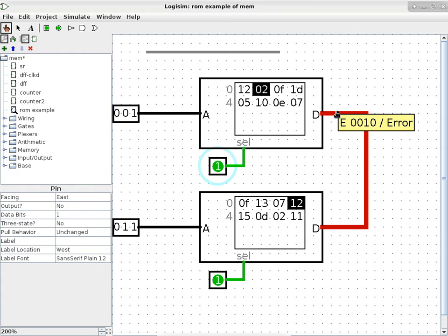And they're connected to the same wire. So we are basically saying this wire and that wire are now connected. What do you think is going to happen? Power going straight to ground. We have a large, quote unquote, large amount of current going from power through the P transistors, the wire, and the N transistors to ground.